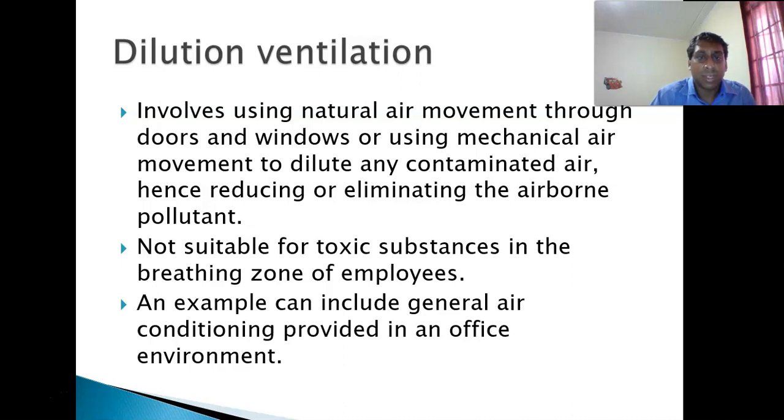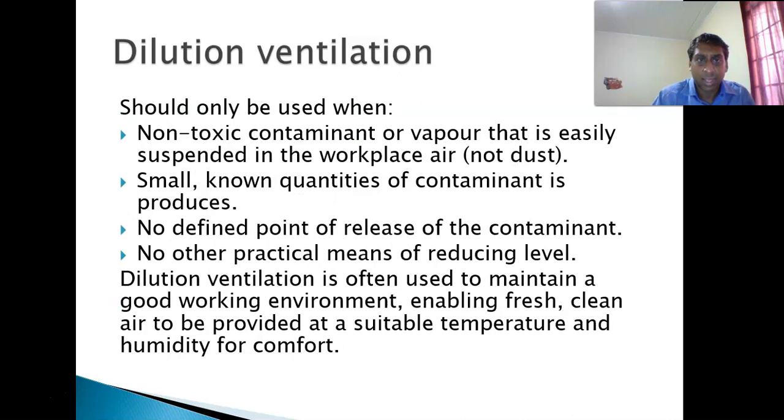So as I click this one here, I remember the question would have been like, when would dilute ventilation be suitable? It should only be used when the contaminants are non-toxic, or vapors that are easily suspended in the workplace air, not dust. Small known quantities of contaminants are produced. There is no defined point of release of the contaminant. There is no other practical means of reducing the level. Dilute ventilation is often used to maintain a good working environment, enabling fresh, clean air to be provided at a suitable temperature and humidity for comfort.